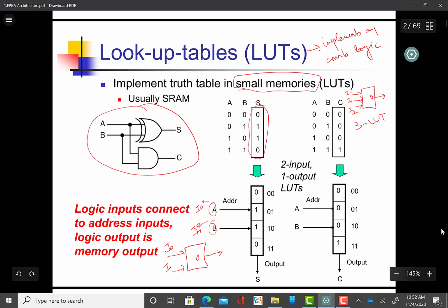you see, this goes into the memory cells of a lookup table. So if it's a 2 input lookup table, it has 4 memory cells. So every one of these boxes is an SRAM cell, and you know very well from your previous course on VLSI circuits that an SRAM cell can store a single bit, and you also studied the transistor level circuit for the SRAM cell.